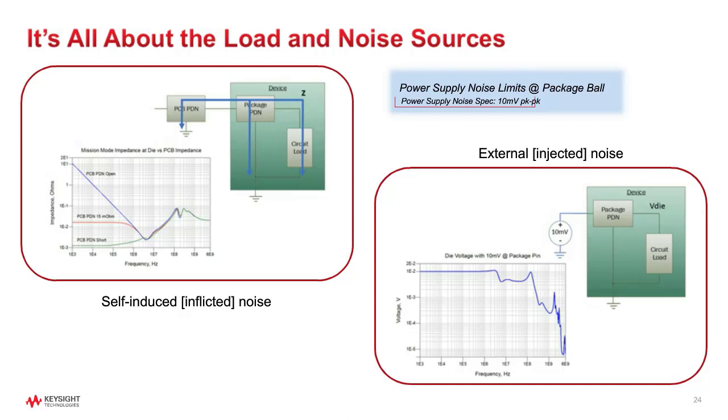The open state with no PCB PDN connected clearly shows the decreasing capacitive impedance slope at lower frequencies that can be used to estimate the internal package die capacitance. This capacitance can then be used to estimate the maximum allowed PCB inductance.